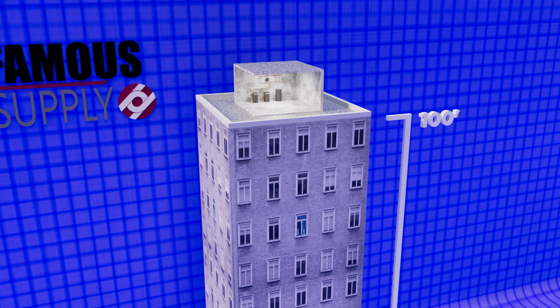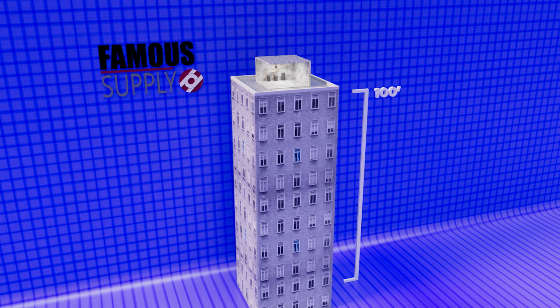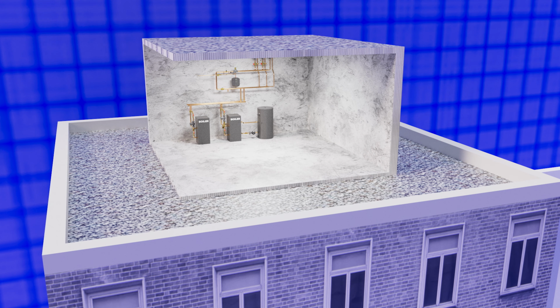If our boiler is on the top of the system and we maintain the system with a standard 12 psi, we can calculate the pressure at the bottom of the system with the same math. 12 psi static pressure plus 43 psi, or the weight of water in the system, equals 55 psi at the bottom. Understanding the weight of water and how we overcome it is a fundamental principle of hydronics.